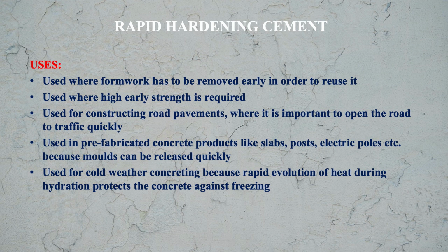And you know that water is very important for completion of hydration process, and without completion of hydration process, the cement will not gain the strength, concrete will not gain the strength. So here it is important that the hydration process is completed quickly. So for that purpose we use the rapid hardening cement in cold weather concreting.